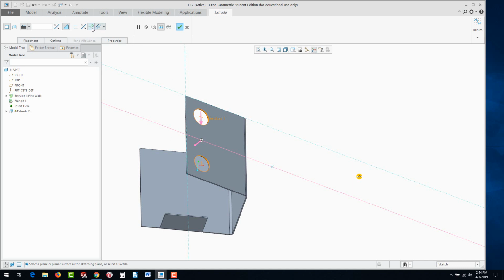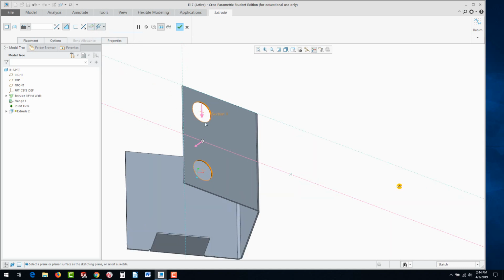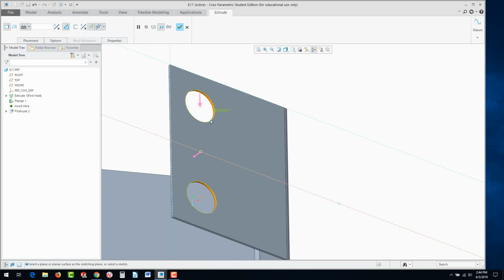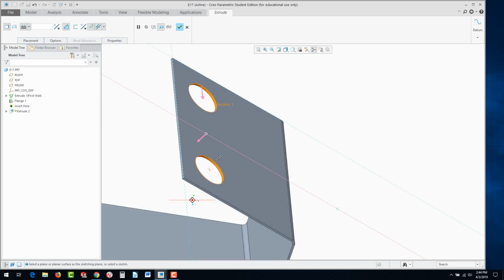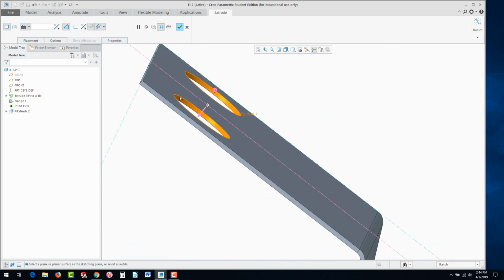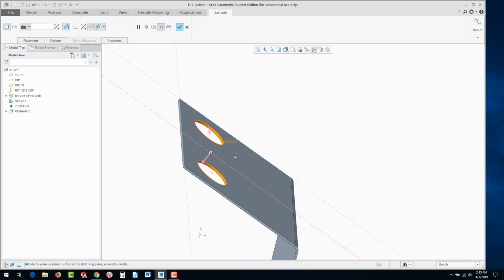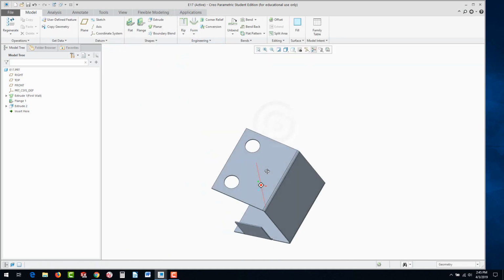They also have here where it's going to automatically create the cut as if this hole was created in its flattened state. If it was created at the angled state, you would actually see little sharp corners on these elliptical type cuts. And with that on there, it automatically makes it straight as if it were cut that way. And this is the ability to adjust it dependent upon your perspective. So really nice set of tools they have there for that. Let's go ahead and hit the green check mark to apply.